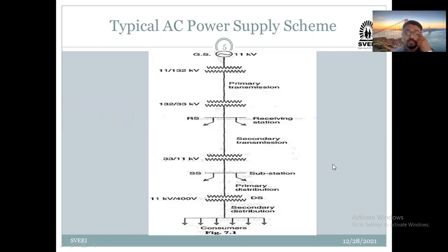It is easy, it is not difficult to remember, and it is not rocket science. You can also remember it like this: the 3 phases that I am showing you on the screen, if you consider a 3-phase 4-wire system, the voltage between any two of them is 400 volt. And whenever you consider any particular line, and you consider this thumb as the neutral, the voltage is 230 volt single phase AC.